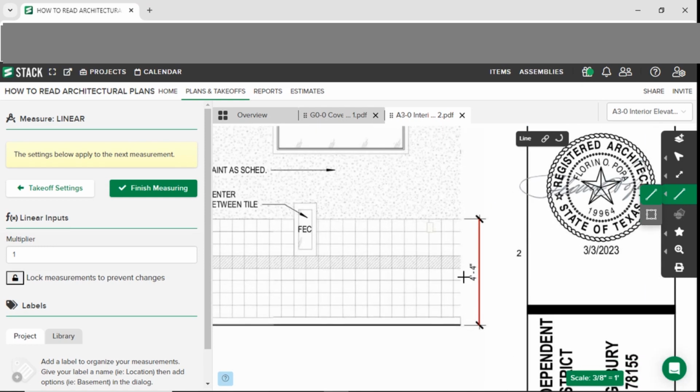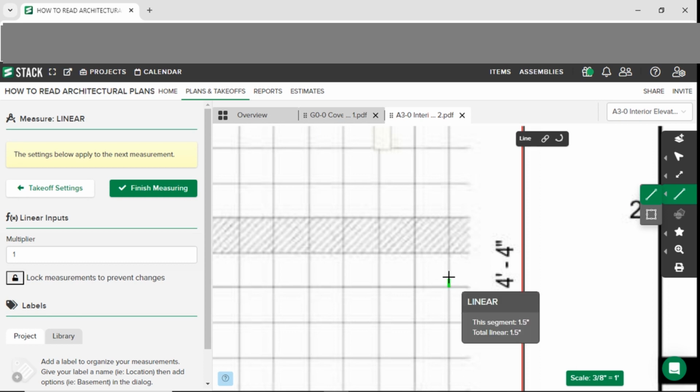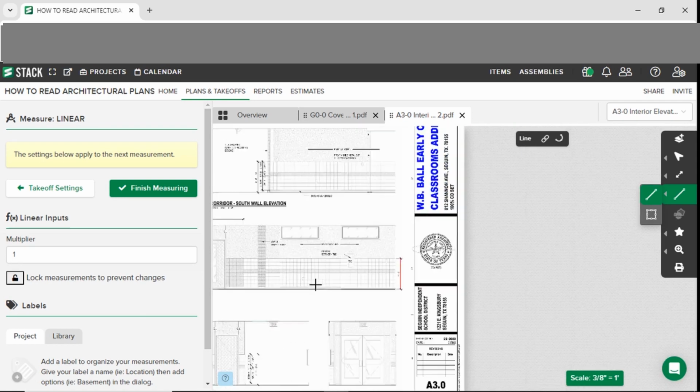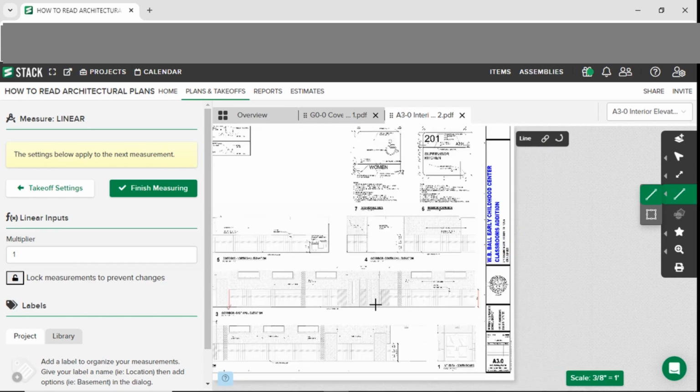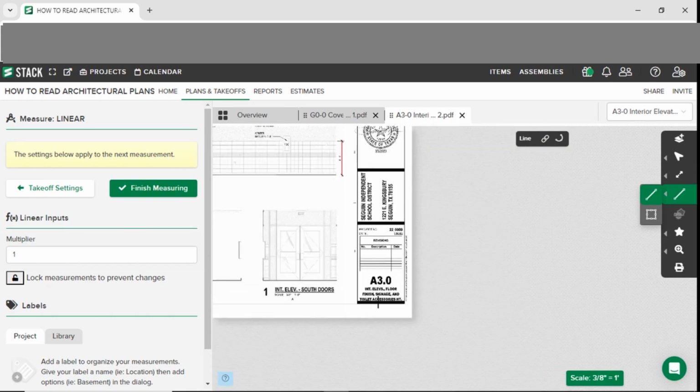So I want to make sure that he also used the right size of tiles. Did he use 4x4s or 6x6s, because it called for 6x6s. Maybe he bought 4x4s by accident. So before it's installed, you check all those details. That's the type of information you'll be able to find on an elevation sheet.